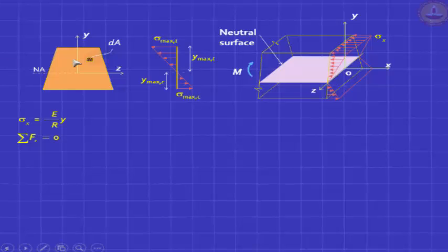If the beam is in equilibrium, every free body of the beam must also be in equilibrium. And so the resultant force, in this case it's only normal force, horizontal force, must be equal to 0. Please note that when we do structural analysis, we actually write these equations with reference to the undeformed geometry. So it's still horizontal, though actually it's curved a little bit.